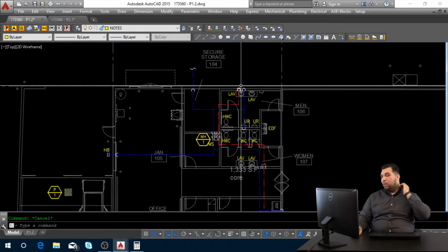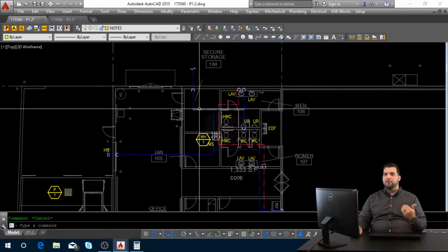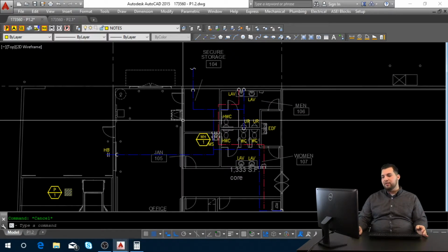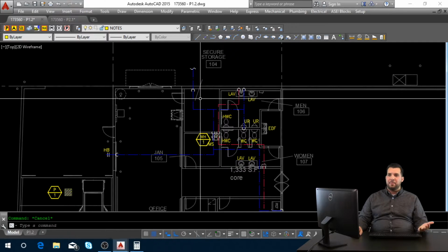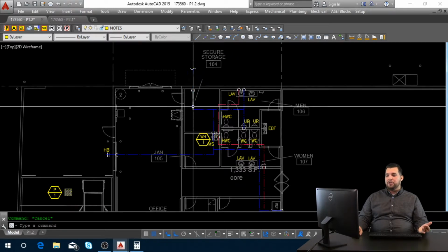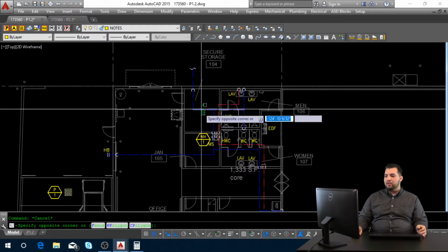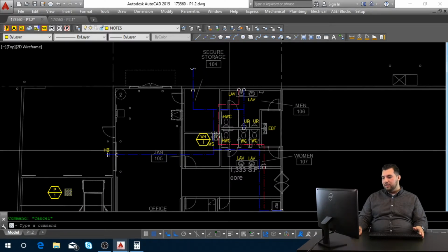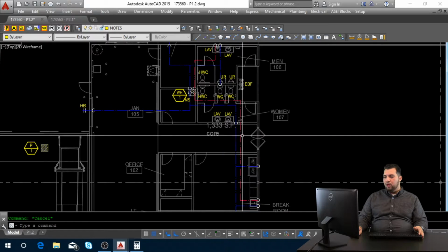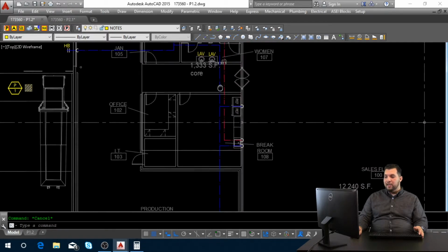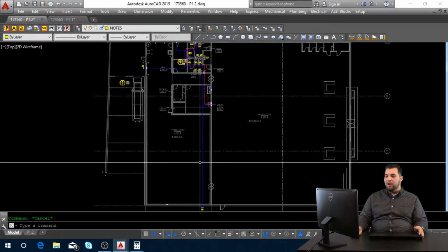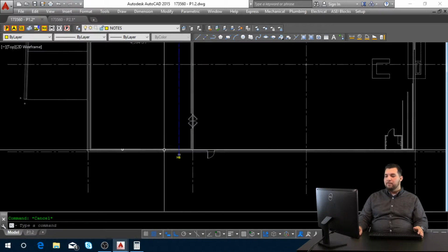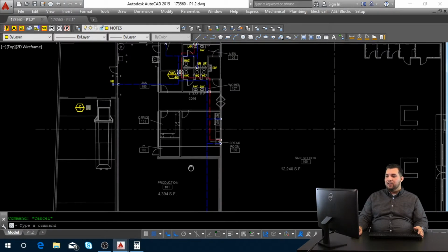So when you're running your water lines, you want to make sure that before you run individual lines, you don't want to just run a line into every single thing. So you want to go ahead and run your main water distribution. So here you can see your cold water. So I went ahead and I ran my cold water and I ran it down, and I just kind of put it through all of our groups where we know we're going to need them, and just kind of ran it all the way to my last fixture. So here's my hose bib. I have my last fixture on there.